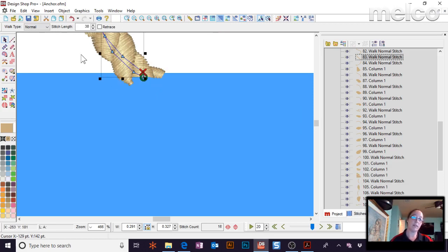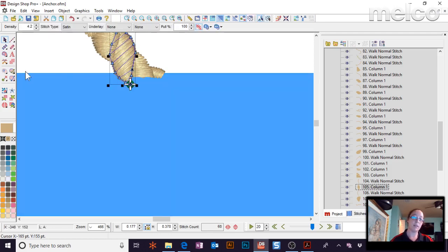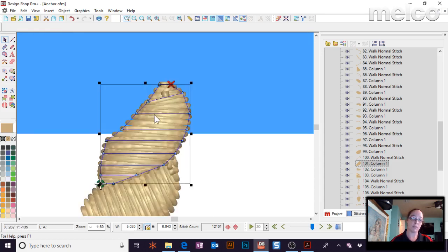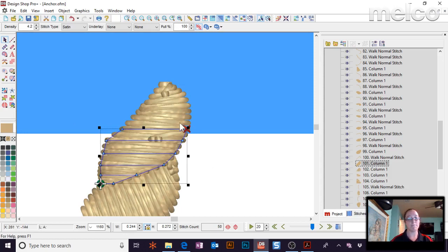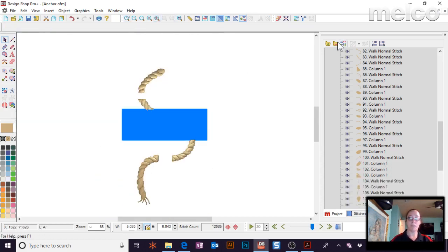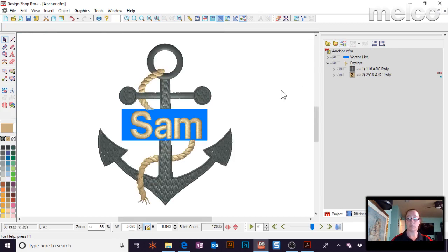On this guy here, I'm going to split element by saying split element at selected points, and delete. All right, so that cleaned up this side. Down here there's a little bit less overlapping, so that one's going to be quicker. Just select the point and say split element at selected points and delete. There. So in just a few minutes we've split that up.